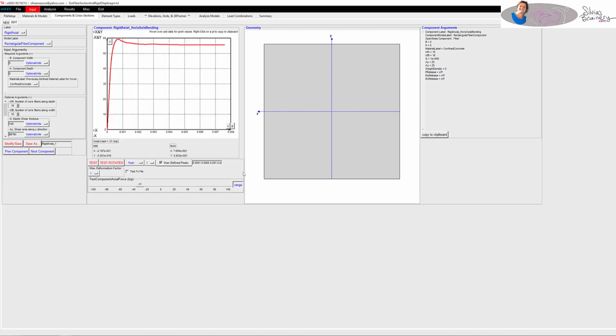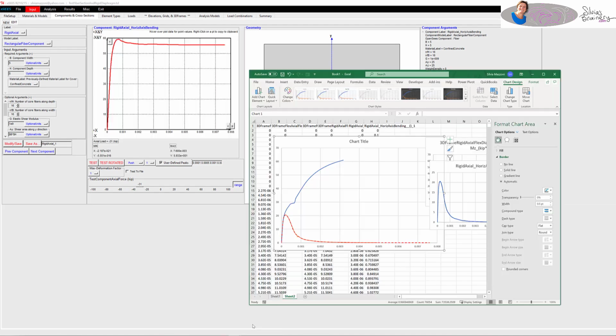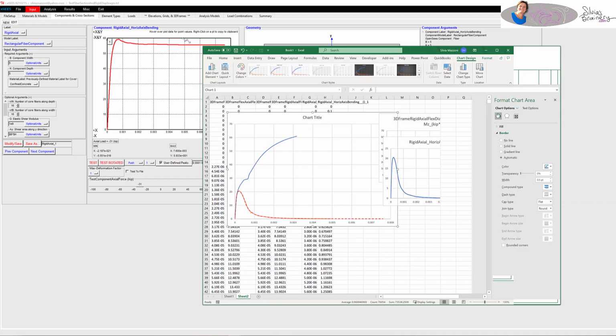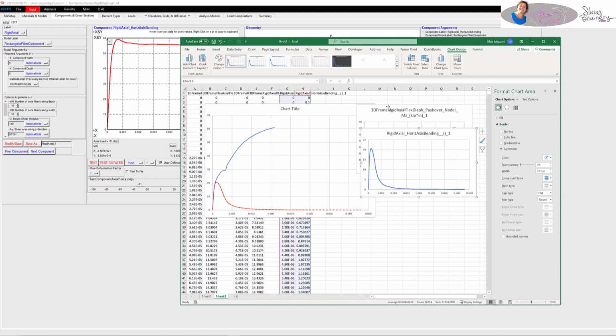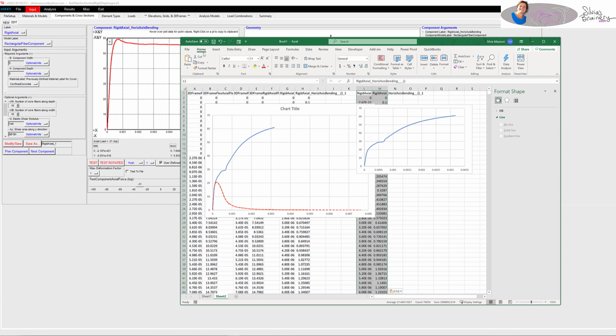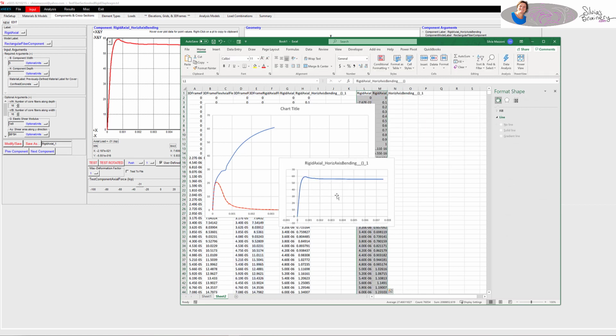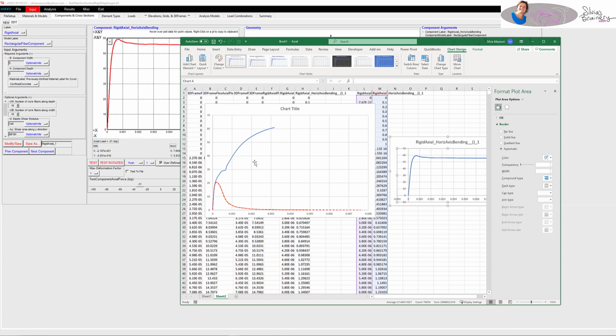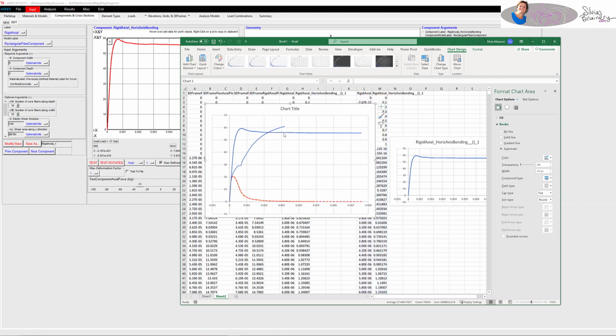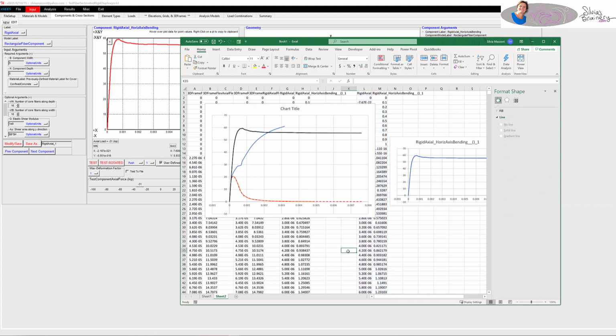I'm going to get the moment curvature response of this fiber section under a constant axial load. So it's not quite representative of what I have in the beam, but it should give me a similar moment capacity to what I cross in my analysis. So if I take this data and paste it here, there it is. You see, the capacity does cross with what the demands were in my beam. And so that tells you that, yes, I'm getting consistent results where I have PM interaction.